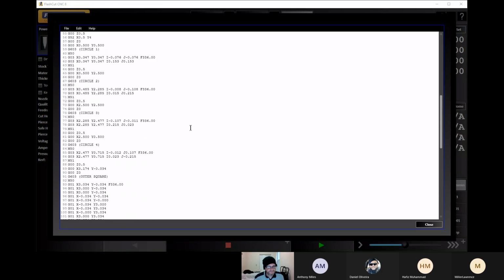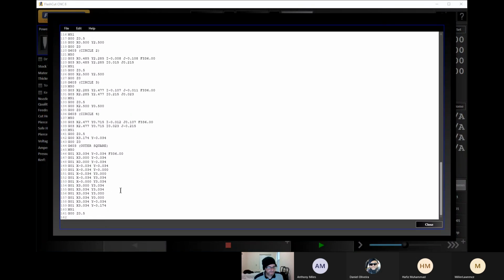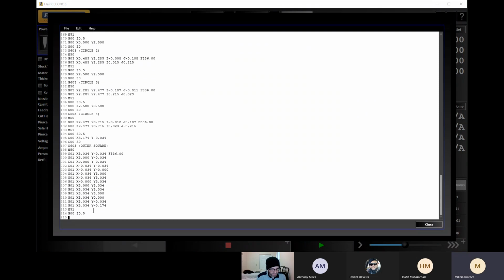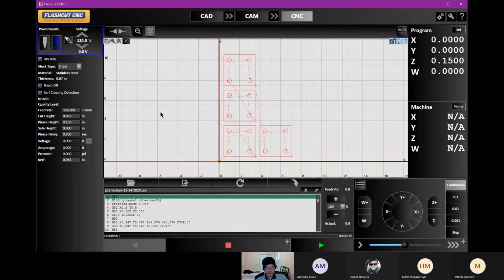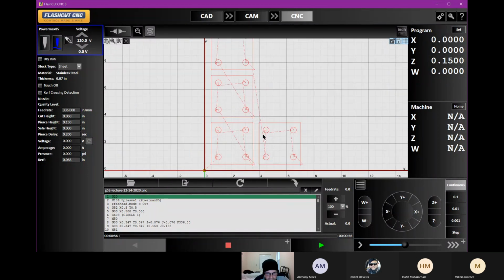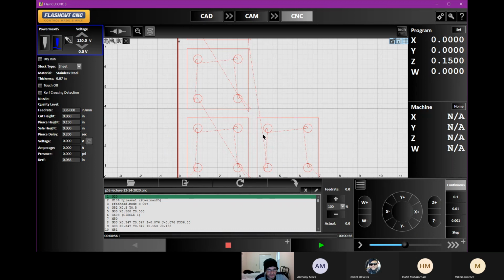Go back into our pencil, go down to the end of the program, type in our new set of coordinates, G52, X4, Y 0.5, put on our G00, bring our torch back down, hit Control V, we save it, we close it, now we got one right next to it, and it looks like the spacing is about equal.